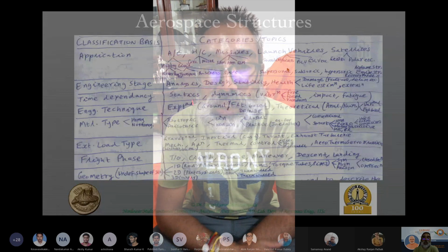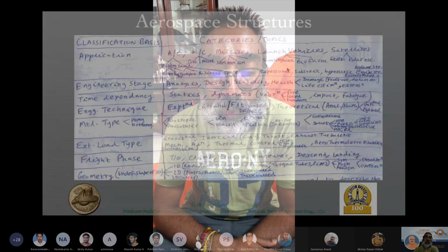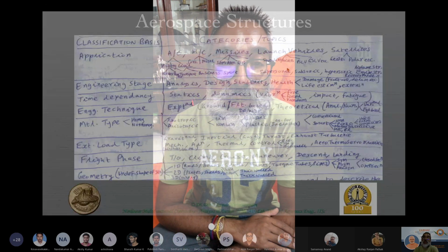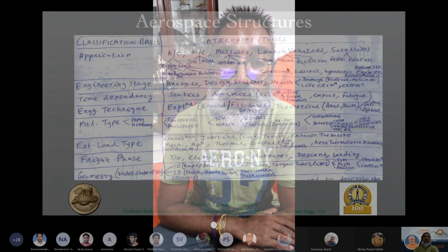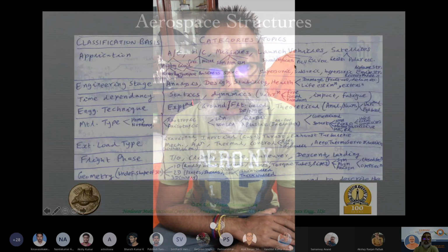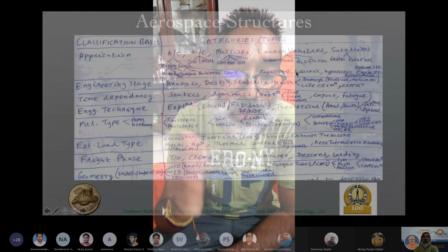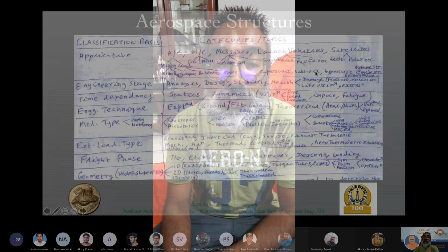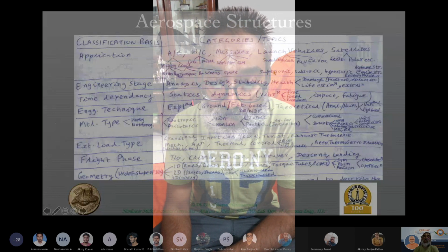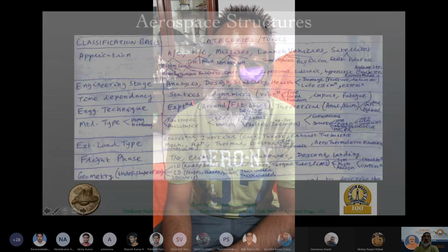So that transonic regime, where it's just about to change over, is also a very specialized region where the aerodynamic loads are going to be slightly different from how you're going to consider supersonic or subsonic designs. So the aerodynamic design itself is going to be very different. The kind of airfoil cross sections used for subsonic have much more rounded leading edges. You could have sharp leading edges, a delta kind of wing configuration for the planform, etc. So that aerodynamic design changes are going to reflect in your structural changes as well.